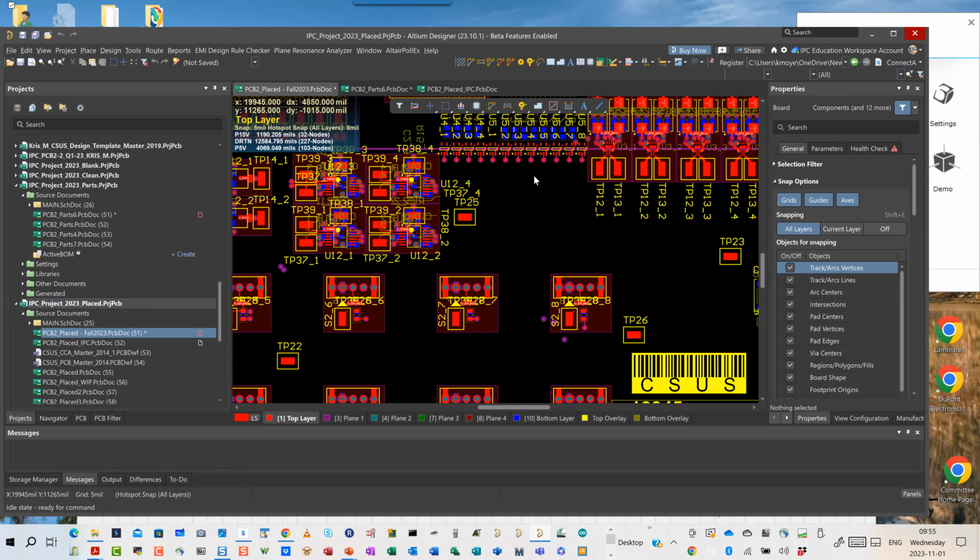But what we're going to see right here is one of the things I did after I got everything placed, so I had the room. I originally had my Schmitt trigger and cap for the Schmitt trigger as part of this room. But then I realized that technically, that is also a device that's straddling the references. The input is referencing the analog return, while the output is referencing the digital return. So I moved all the Schmitt triggers and their capacitors so that they are directly on top of the split boundary right here.